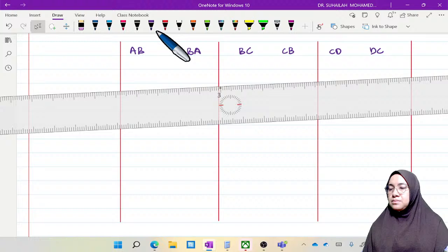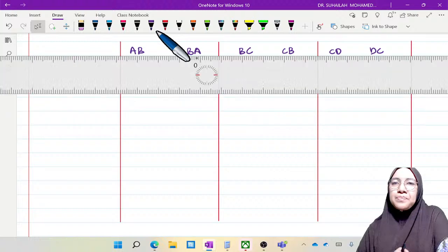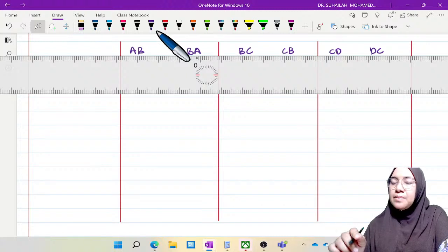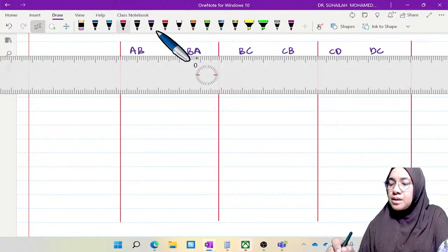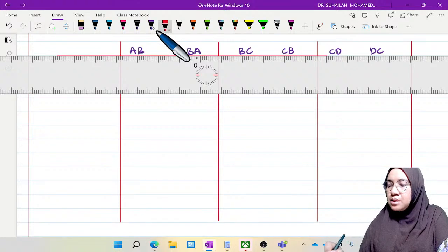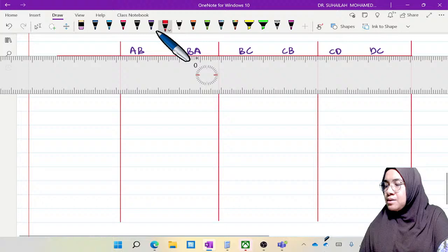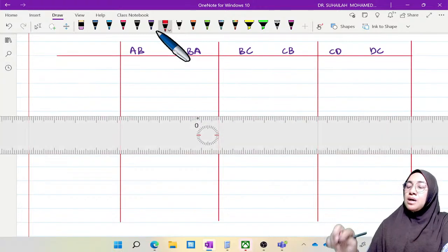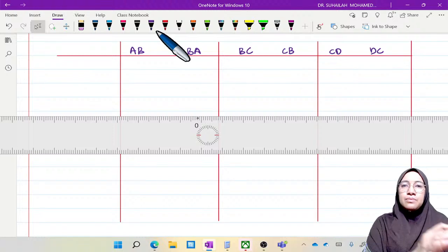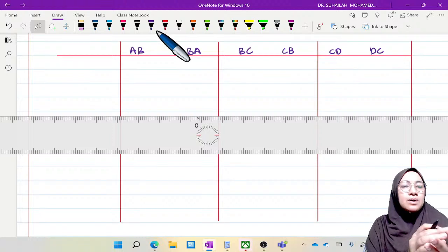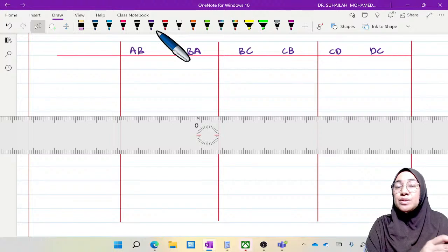In this table, I actually want to put K and DF directly. We have to know that the moment we distribute is the joint moment we calculate by finding the moment times the distribution factor.